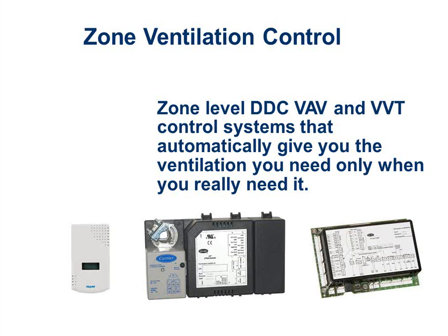So if I have, say, a 20-zone VAV system, I'm going to end up with 20 CO2 sensors on the wall right next to the temperature sensors, or even better, in the same plastic enclosure as the temperature sensor, wired back to their local VAV boxes that are controlling those dampers. Then we're going to look at those 20 VAV boxes and say, are any of you guys not meeting your CO2 set point, and who's the worst one? Okay, the worst one, you get to dictate the outside air ventilation rate at the air handler.